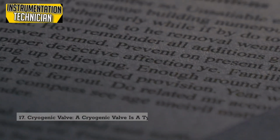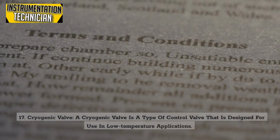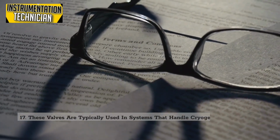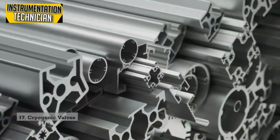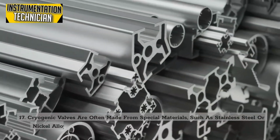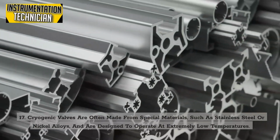Cryogenic valve. A cryogenic valve is a type of control valve that is designed for use in low-temperature applications. These valves are typically used in systems that handle cryogenic fluids, such as liquid nitrogen or liquid oxygen. Cryogenic valves are often made from special materials, such as stainless steel or nickel alloys, and are designed to operate at extremely low temperatures.